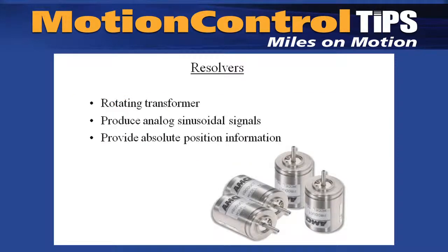A resolver is essentially a rotating transformer that produces two sinusoidal signals. These signals indicate the absolute position of the motor. Electronic circuits convert this analog signal to a digital signal for processing by the motion controller.